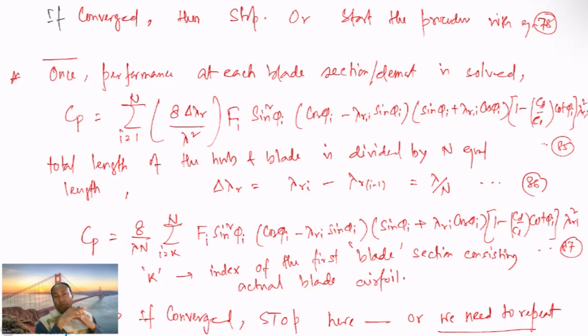So primarily you have to select the airfoil, you need to select some kind of a twist, you need to see the variation of the chord. Obviously once you select the airfoil at different sections, then the chord variations from hub to tip, and then considering those losses and factors, the induction factor is important, tangential induction factor is important.